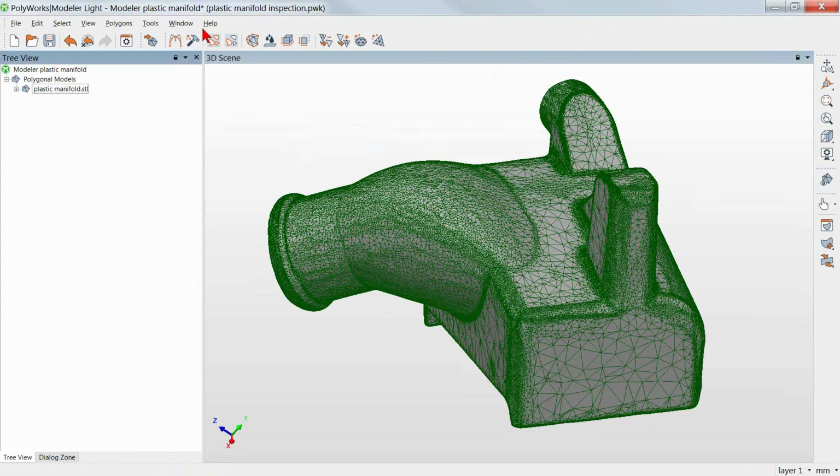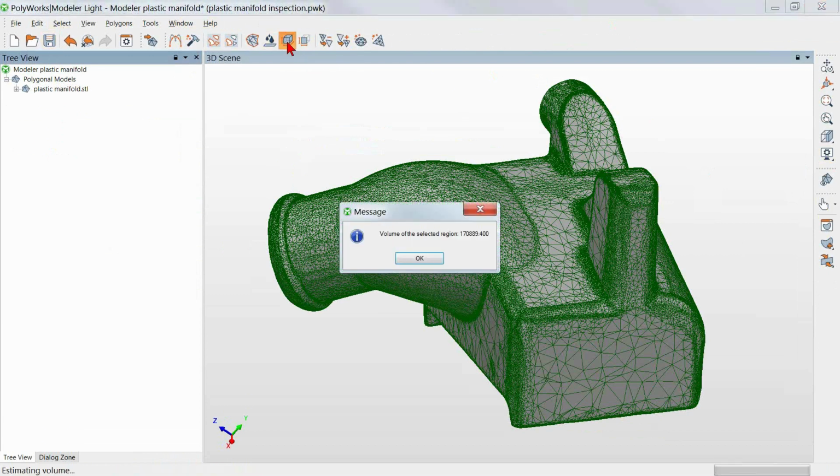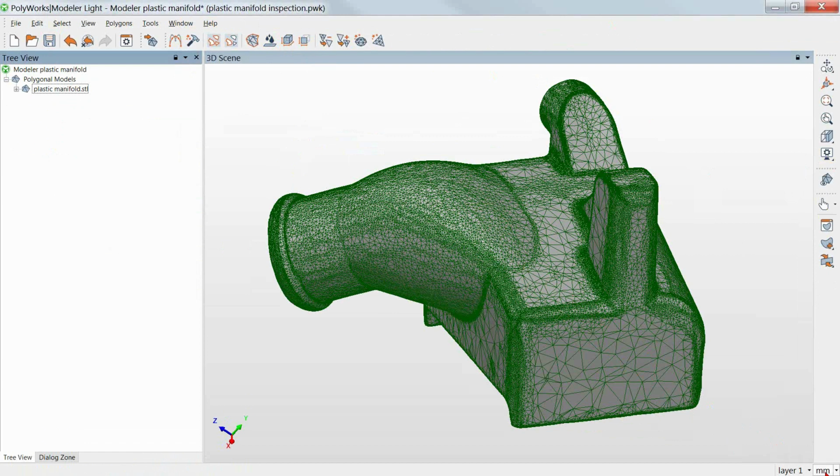Yes, sure can. So when we're dealing with volume, this is one of the things that always pops up in class. And Carol's always really good about giving these questions that she likes to get me with sometimes when I go a little bit quick. When we calculated the volume, you don't see units here. And one of the things I always point out to everybody within a training class is the working units, even though that disappeared, is actually down here in the lower right-hand corner. So you can see that we're in millimeters.